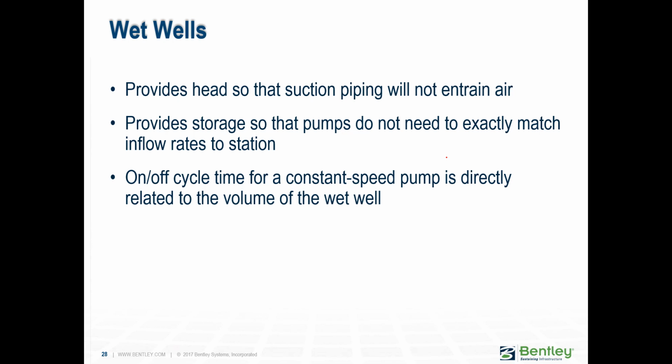If you're turning your pump on and off, it's a constant speed pump, obviously, because the thing with variable speed pumps is that they don't really need a wet well, right? Because a variable speed pump is always on, so you don't really turn that pump off, and you don't really need that storage. So wet wells are very important when we talk about constant speed pumps.